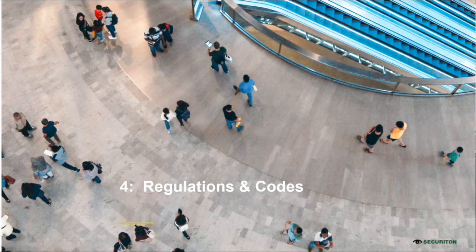You can use this system as a standalone as well, because it has a detector chamber inbuilt, and all the signals come back to the detector unit, and you will find the signals on the screen of the aspirating smoke detector. If you are using a fire alarm system, then you can connect it with the fire alarm system as well. Okay, thank you very much. We don't have any further questions at this stage, so please proceed.